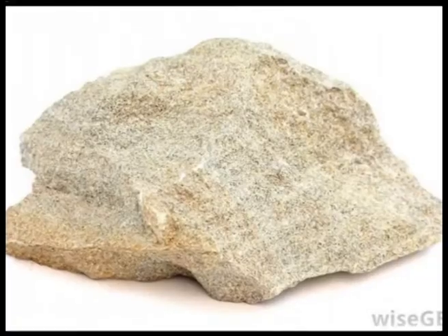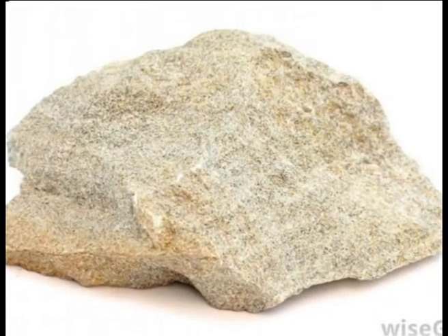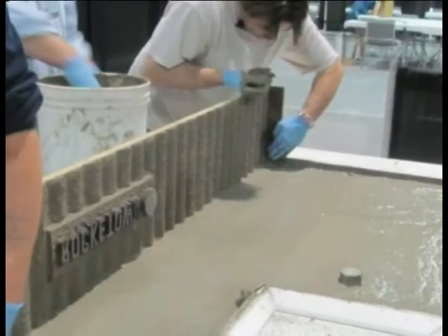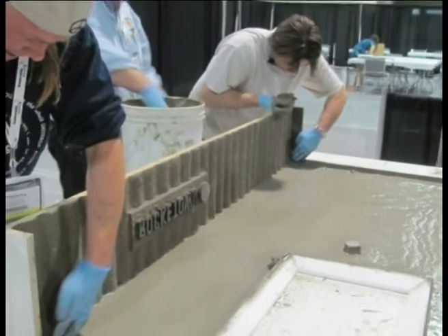Sandstones. Massive sandstones consisting of closely interlocking and angular grains and free from structural defects find extensive use as building stones. Ferruginous and calcareous varieties should not be used for exterior work, especially in industrial towns. Argillaceous sandstones are generally weak in character. Massive varieties with a siliceous cement possess sufficient strength and are easily workable.